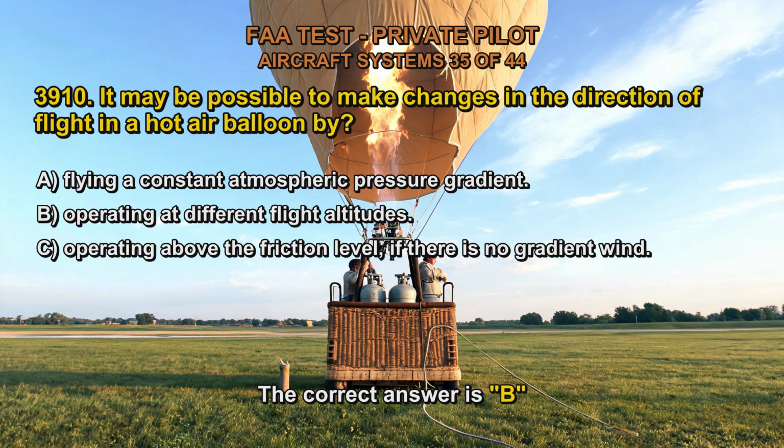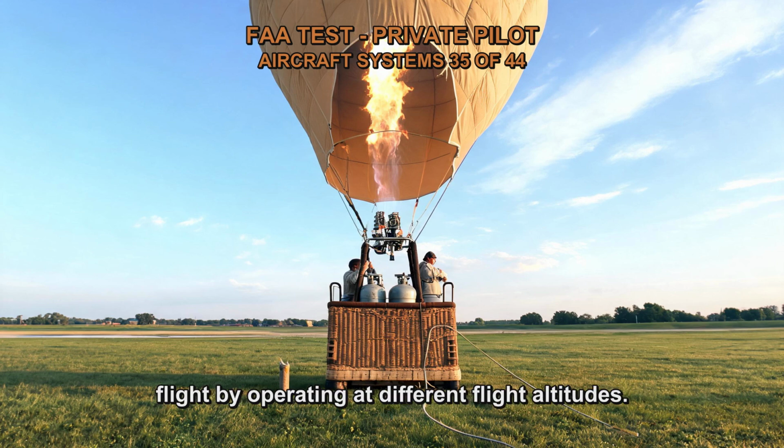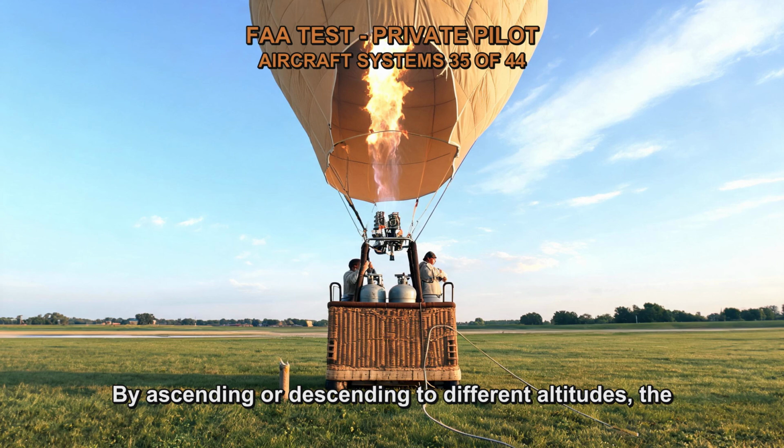The correct answer is B. In a hot air balloon, it may be possible to make changes in the direction of flight by operating at different flight altitudes. The wind direction can vary at different altitudes due to the presence of gradient winds or other atmospheric factors.